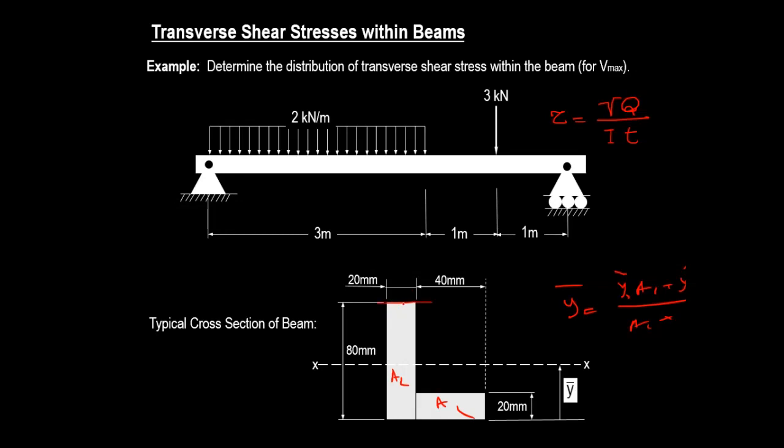If I make a section here, there would be a zero area at the top and something at the bottom. So at that top surface, the Q is zero. So it tells me the shear stress can't be maximum there. It is zero over there. So the next point is, what about here? If I split that here, I would have a block here and another composite block at the bottom. So it would be crazy if I decide to calculate that from below. I know that this should give me eventually the same answer as that of the top.